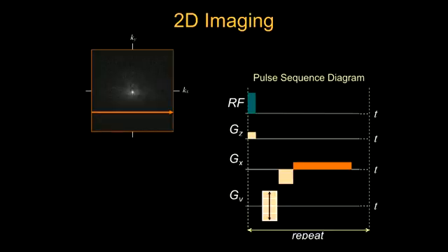So just getting one line of the signal is not going to be enough. You have to get all the necessary information to decode all the 2D information together. The way that works is to design a pulse sequence diagram that traverses all these k-space locations, records all the required information, and then applies the Fourier transform to get the imaging information out. In other words, you can see the signal equation as recording all the necessary k-space information, and this k is controlled by the gradient.